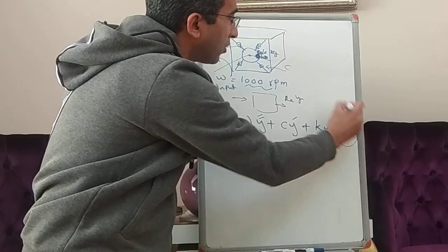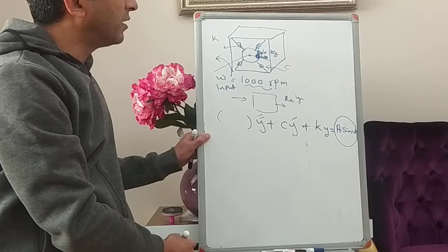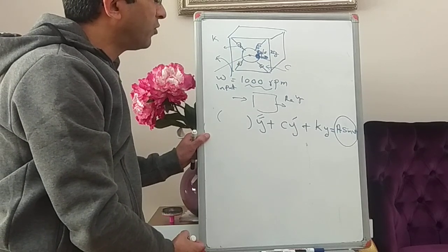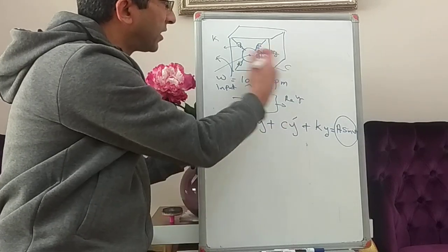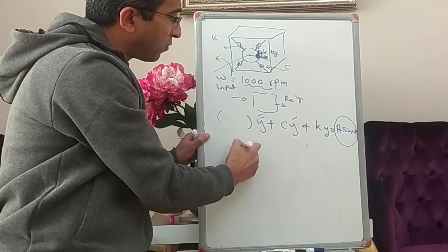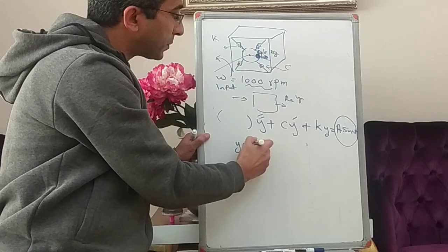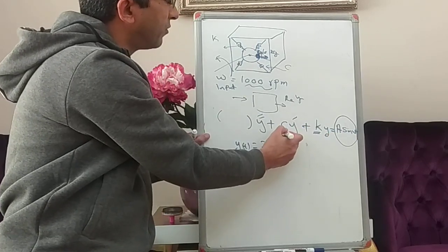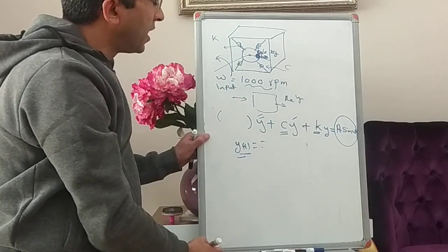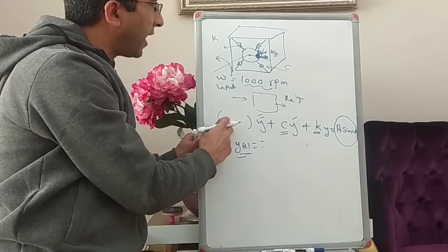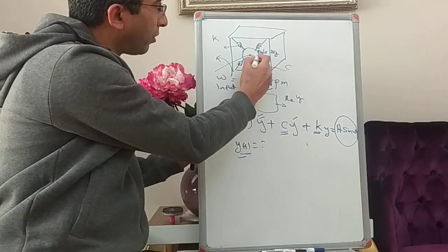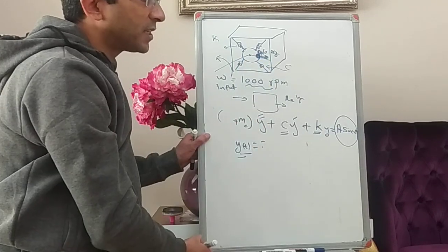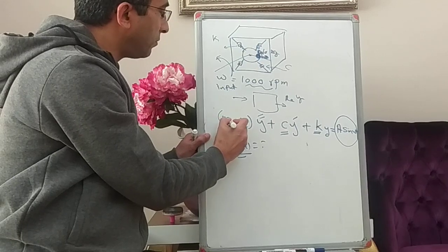So this is a sinusoidal excitation force acting on your system, and if you want to minimize the lateral or vertical vibration, which is your y function, you have to choose the suitable spring constant k, the suitable damper, and also the total mass, which is the mass of the cloth, I will call it mc, plus an additional mass md.